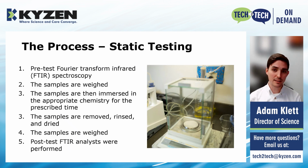So we'll start the test off by taking this pre-test spectrum, and then we'll weigh the samples to get the mass of them. Then we're going to be immersing those samples in the solvent or the appropriate chemistry for the prescribed amount of time, and seeing how much of the chemistry absorbs into the material or how much of the material dissolves into the chemistry. After the prescribed amount of time, the samples are removed, rinsed, dried, and then we weigh them again and test to see how much mass the sample gained or lost. We'll then do a post-test FTIR analysis to look at the changes between the chemistry of the tested and bare samples.